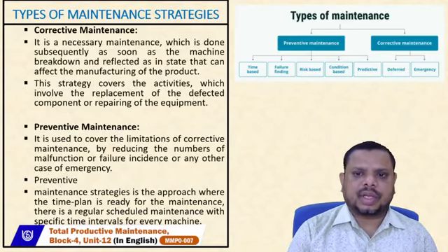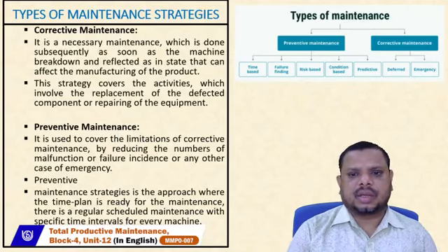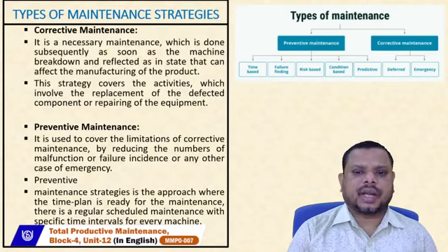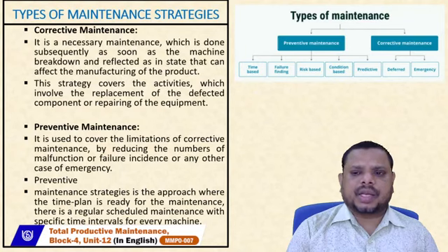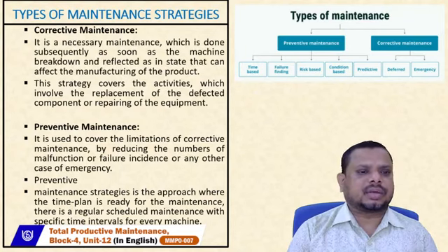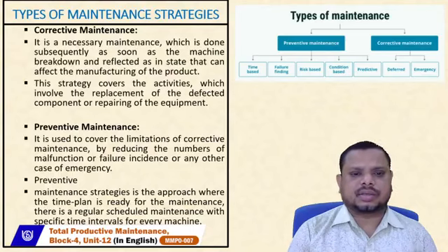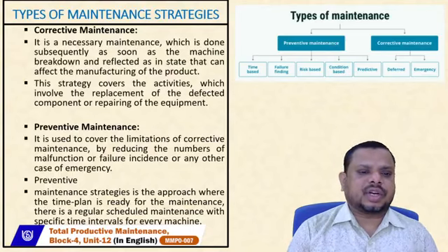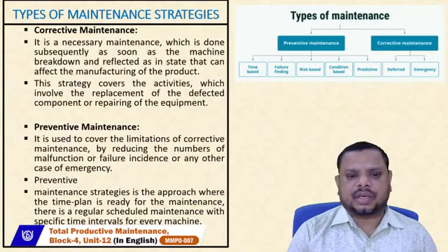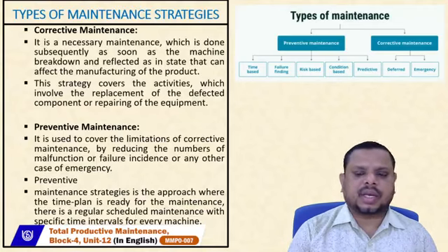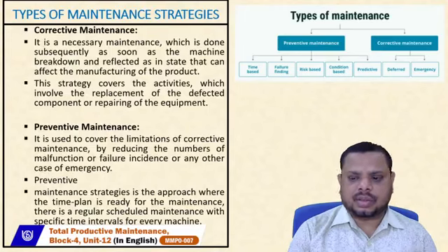If you compare this classification of maintenance, preventive maintenance includes time-based maintenance and failure finding. It is also risk-based, and it includes condition-based monitoring and predictive maintenance. But corrective maintenance is done when emergencies arise, that is, when the equipment or machine is damaged and needs repair or replacement.